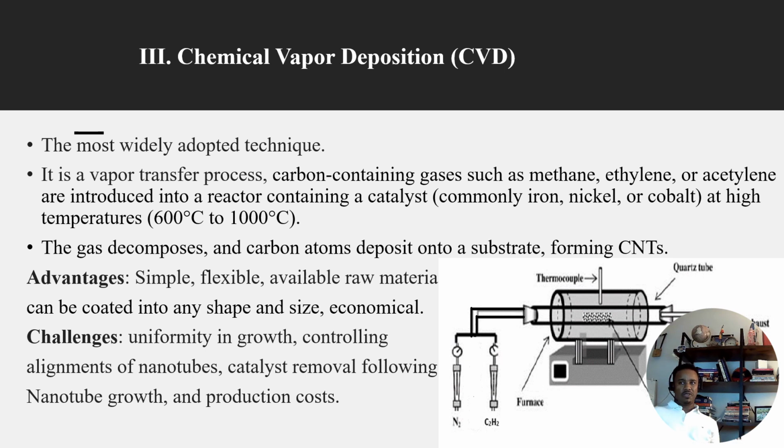And of course, CVD is economically competitive, which makes it really attractive among all methods we have seen so far. However, there are also a few challenges, like achieving uniform nanotube growth across large areas. That's one of the hurdles facing this technique. Energy consumption is relatively high due to the elevated temperature requirement. Like we said, we need a temperature between 600 to 1000 degrees centigrade, so obviously, it requires a lot of energy.